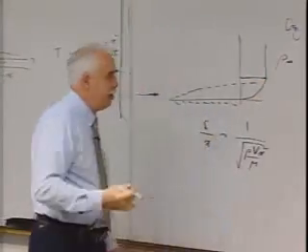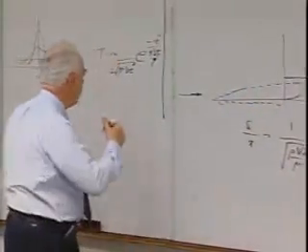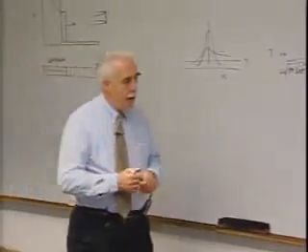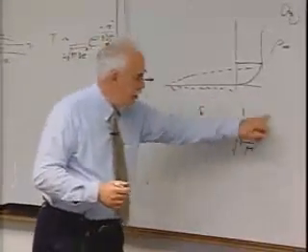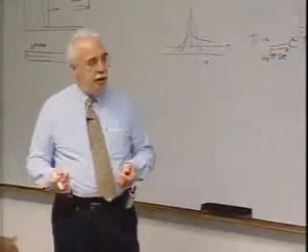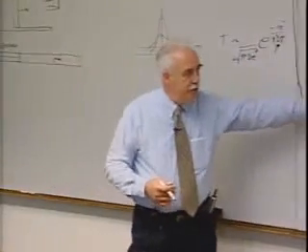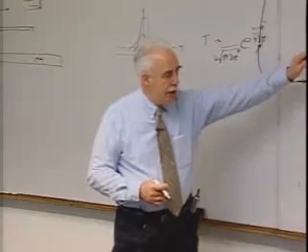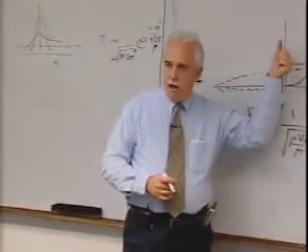Whether it be the thermal diffusion associated with heat transfer, or the diffusion associated with the shear, same phenomena. When I first found this in fluid mechanics, I was told, well, that was empirical, and basically it is, but it really goes back to the fact that if you approximate the Navier-Stokes equations in this one-dimensional situation, you basically have a convection in this direction and a diffusion in the orthogonal direction.